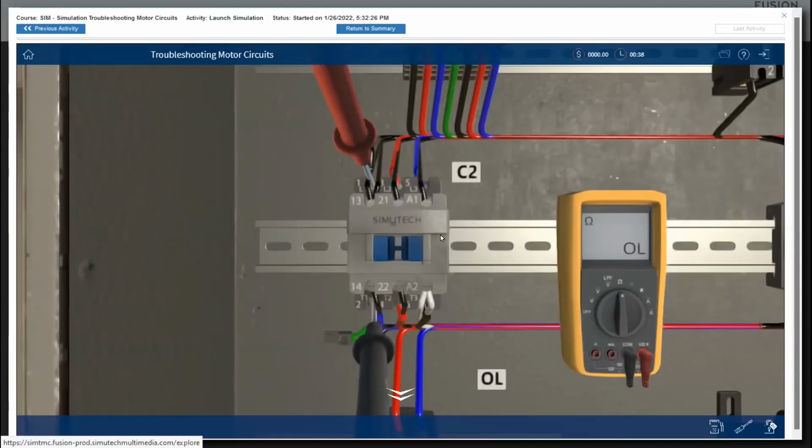What you do not want to do is try to start a motor by pushing this in like this. We're only doing this because the power's off. This is important. I know out of the 246 people we've got listening to this, probably 245 of us have done it, right? Push that in to see if the motor starts. And from a troubleshooting standpoint, it makes perfect sense. If we push that in and the motor runs, well, we know the motor's okay and the contactor's okay. And we have 3-phase power and we don't have 1 fuse blowing ahead of this.